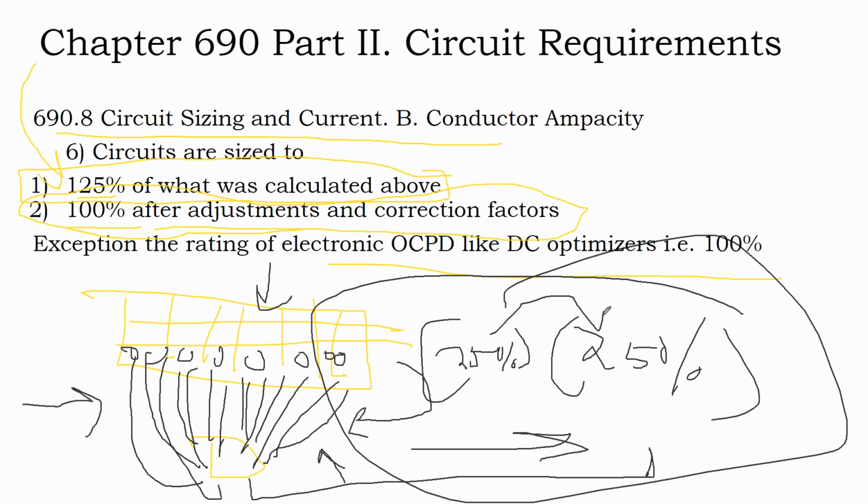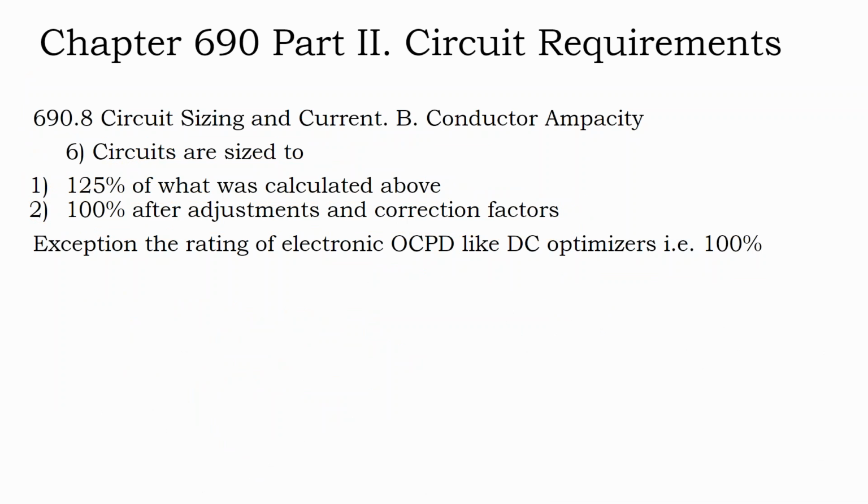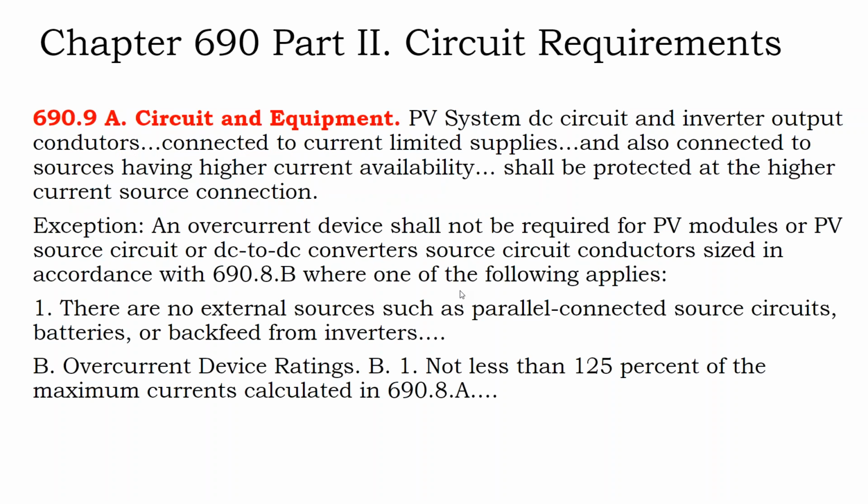But solar, you have that additional protection to account for all of the extreme temperature differentials involved with solar, which you could just go and calculate on your own too, if you wanted to, or you could use these control boxes and then you're right into just normal electrical sizing, where you take the maximum output of the device and add 25% to that, and that's your design ampacity.